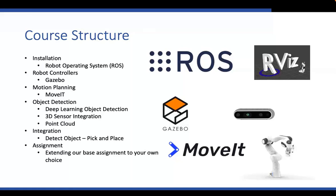Then comes motion planning. What is motion planning? Now you have a robot that you built in Gazebo. You put it in a ROS environment, and how do you want to move from point A to point B? If you want to move from point A to point B, you need to know what path the robot should take based on its joints and how capable it is of moving from point A to point B. MoveIt is an open source library that is integrated with ROS so that we do not have to rewrite all this inverse kinematics and path planning algorithm ourselves. We just need to know how to use it and whichever feels best.